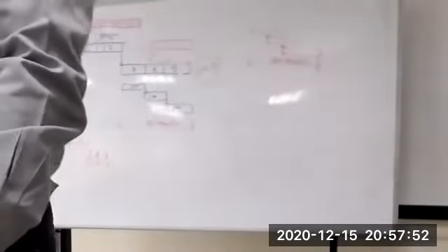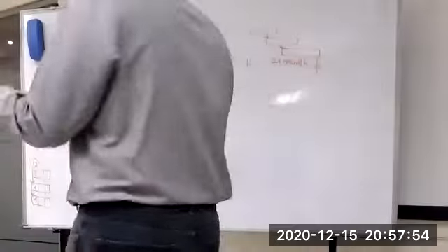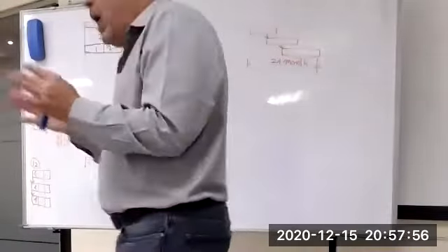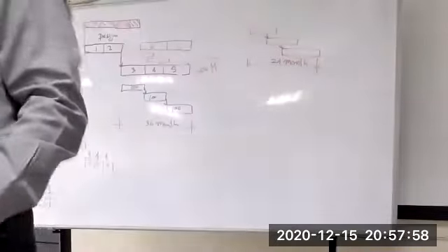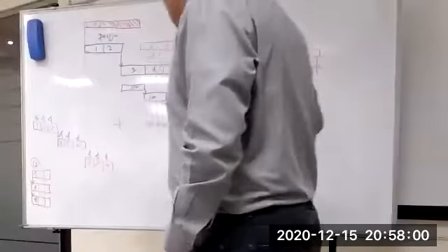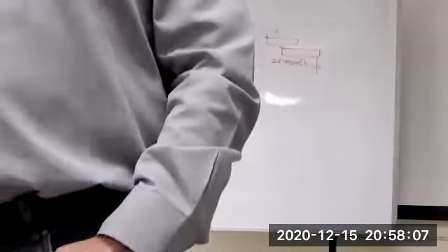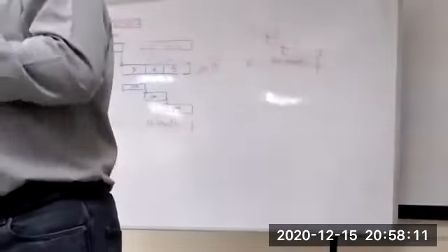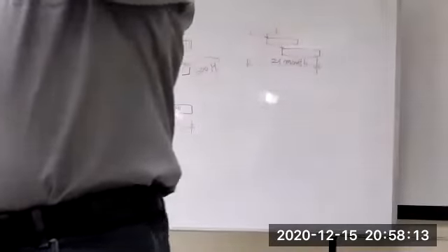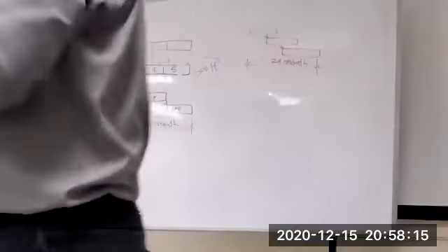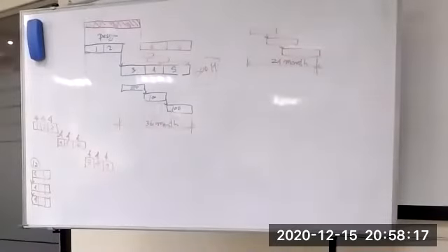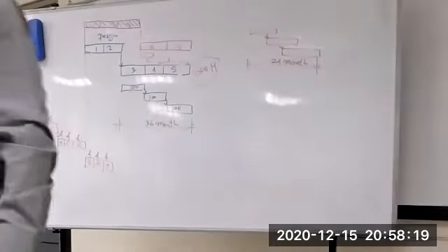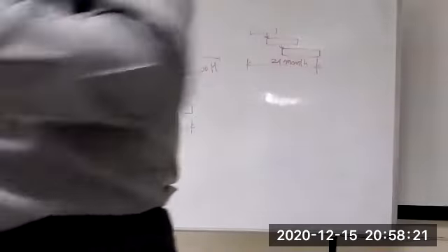you need to make a recovery program, what we are going to do is compress all the critical activities by 2 techniques: fast tracking and crashing. Crashing, what to do? How many activities in the critical path? Assume 3 activities. One of them is 6 days, and you need 20,000 man-hours. Assume to make it in 3 days, what you have to do? Make it 40,000 man-hours. Compress now.